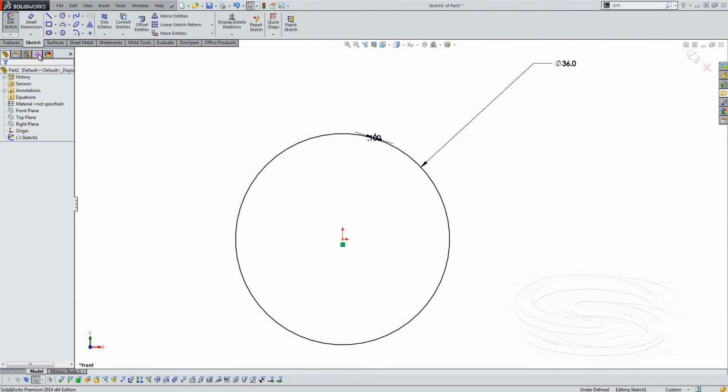Is it a cheat? A little bit, but in order for it to be rolled, we do need a split in there. You could make that split really, really small. I've gone down as far as 0.001, just trying to simulate that gap. Well, we've got that gap added.